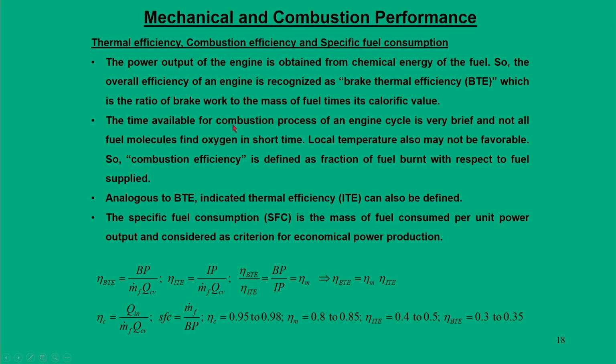Apart from this, we are now going to discuss thermal efficiency, combustion efficiency and specific fuel consumption. So, this is all about the mechanical aspects. Now, we are bringing fuel into the picture. When we bring fuel into the picture, we define 3 terms. First, the brake thermal efficiency of the engine, which is nothing but the ratio of brake power to the total fuel heating value. So, this is the output that we get from the engine, and this is the input we provide in terms of the fuel, that is m dot f into QCV, where QCV is the calorific value.